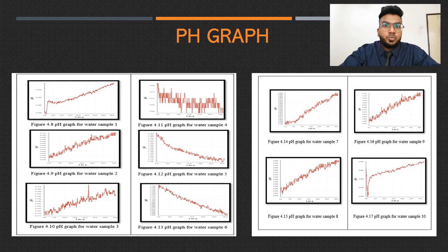Although humans have a greater tolerance for pH levels, drinkable levels range from 4 to 11 without causing any significant problems. A pH greater than 11 might irritate the skin and eyes, and less than 4 can cause the same problems. A pH value less than 2.5 will permanently harm the skin and organs. Lower pH value increases the likelihood of mobilized harmful metals being absorbed even by humans, and pH values more than 8 cannot be disinfected efficiently with chlorine,